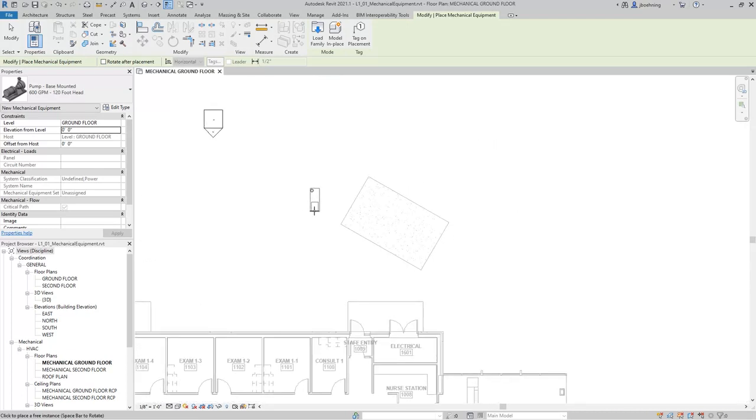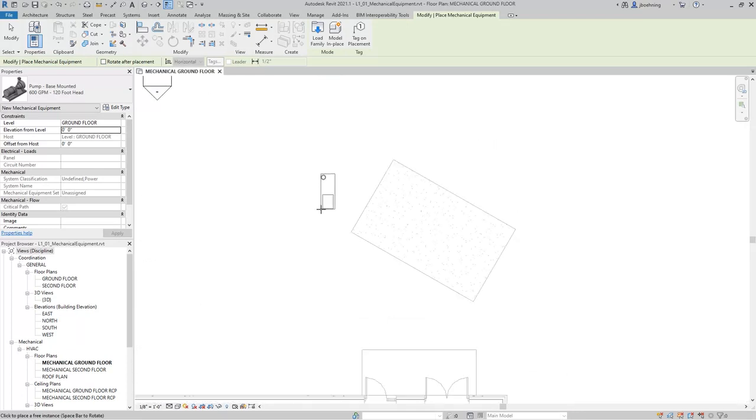And in this case, this foundation slab is at an angle. There are many buildings that have portions at an angle, or even certain rooms that are at an angle. And if you need to align equipment to that angle, maybe it's the angle of a housekeeping pad or a wall or even a floor, you can hover over the edge or a line on that component and then press the spacebar, and the component will rotate in increments relating to the angle of whatever you're hovering over.